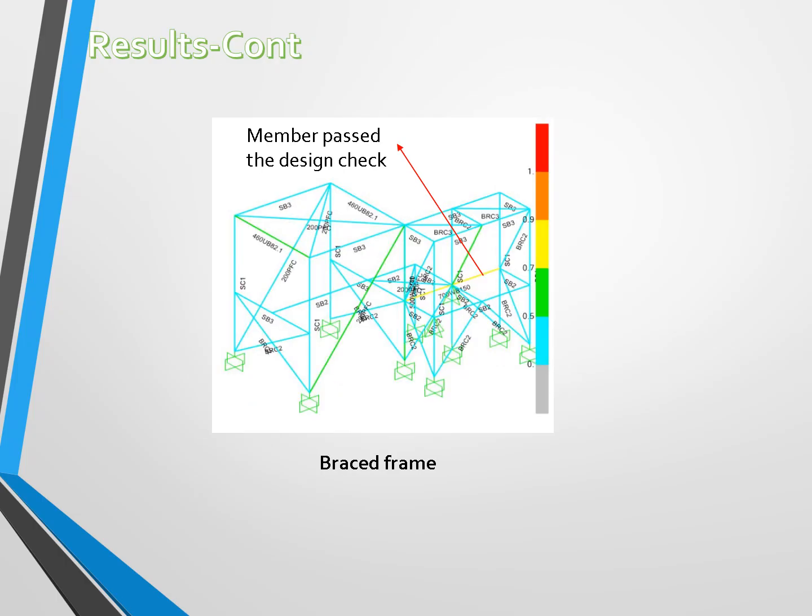Then we introduced the diaphragm as another type of lateral load resisting system, and in the next tutorial we can talk about the design of diaphragms, which are flexible and rigid. So this is the roof diaphragm, and these are the diagonal bracing and K bracing, and here is the inverted V or chevron. Different types of bracing are used in this braced structure in order to manage the cost and the bracing system.